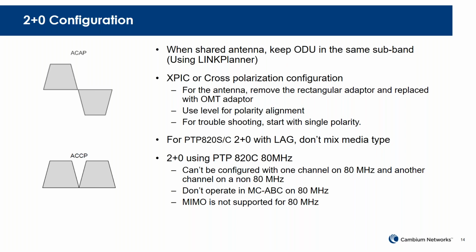Okay, and one other trick to use for your XPIC installation: if you follow the user guide, many experienced installers will try to rotate the antenna to a point where they get an optimal XPI number, and they spend a lot of effort.